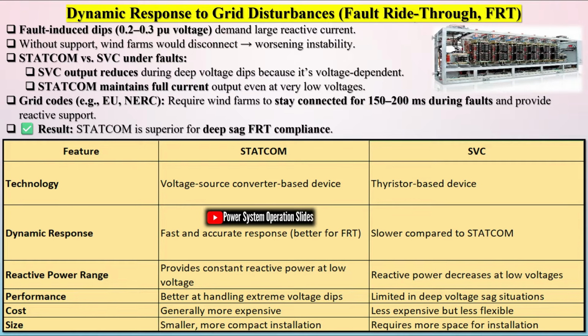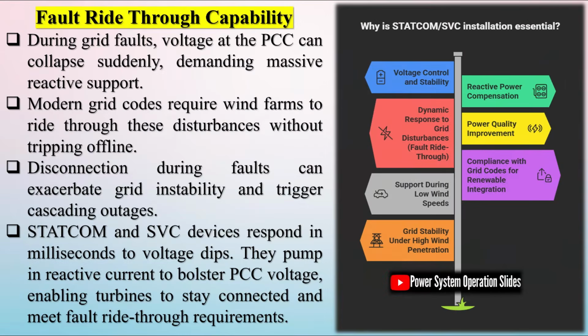When installed along overhead distribution lines, especially near problematic inductive loads, they can inject reactive current rapidly during and after faults. This fast response helps restore voltage levels quickly, mitigating the effects of FIDVR and preventing voltage collapse. Beyond fault recovery, Statcoms also contribute to reducing transmission and distribution losses, enhancing overall system efficiency and reliability.